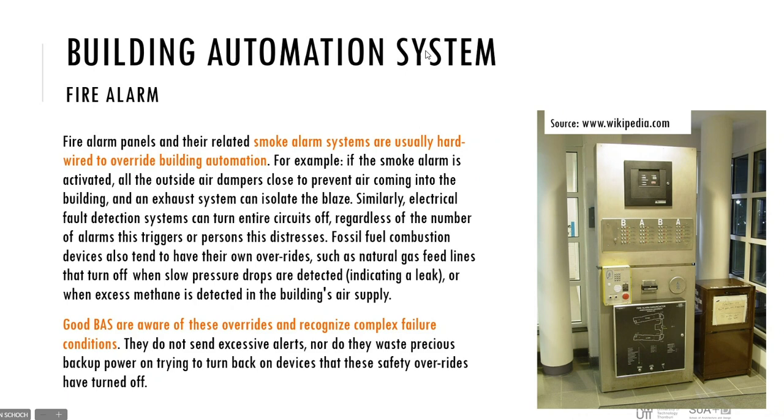And again, the building alarm system is usually related to the building operators, meaning it should be accessible 24 hours, not only to the building operators but also to the fire department. And when they come, they can turn certain equipment on and off and get access to certain areas of the building that may be shut down.